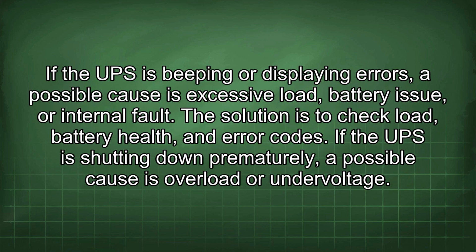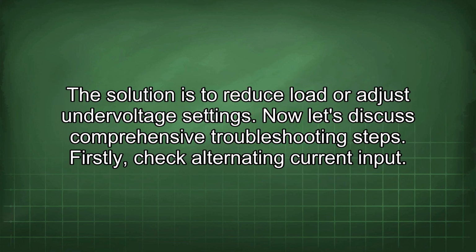If the UPS is beeping or displaying errors, a possible cause is excessive load, battery issue, or internal fault. The solution is to check load, battery health, and error codes. If the UPS is shutting down prematurely, a possible cause is overload or undervoltage. The solution is to reduce load or adjust undervoltage settings.